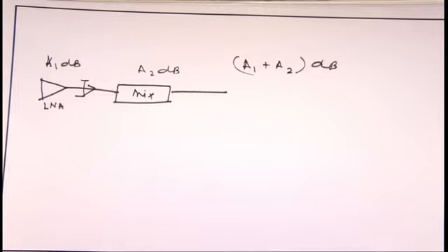So, the next course is you have to actually match again the output impedance of your LNA with the input impedance of the mixer, fine tune it to get your expected gain, which will come from the superposition of the two. For example, 16 dB for the LNA and your mixer is giving you say 2 dB gain. So, you are expecting 18 dB gain.